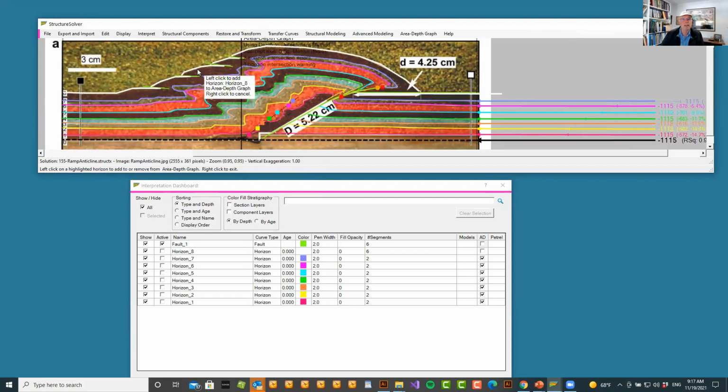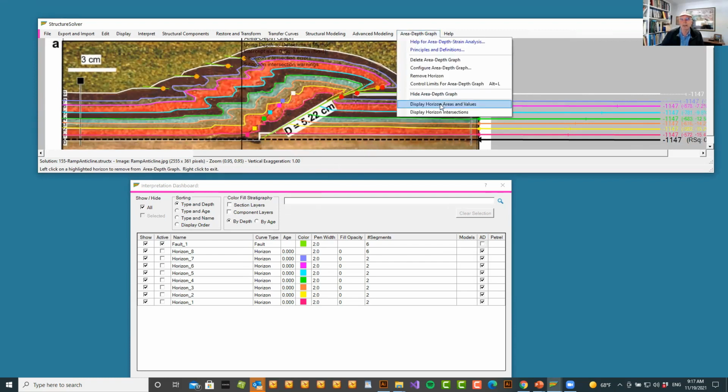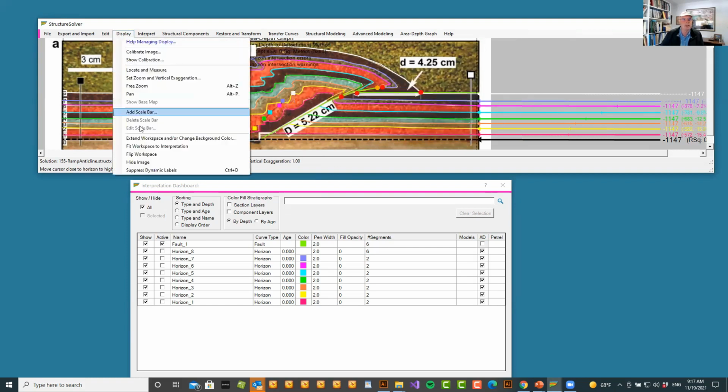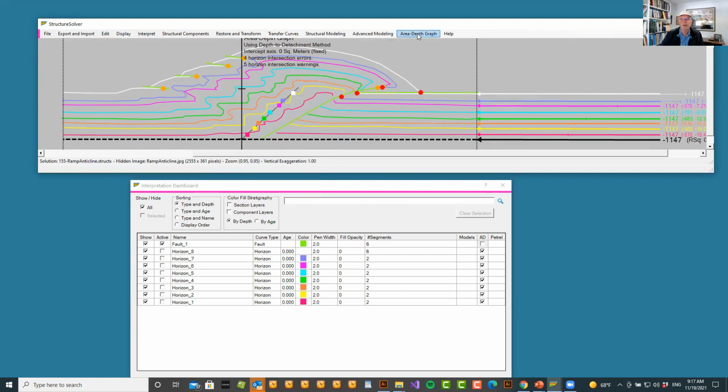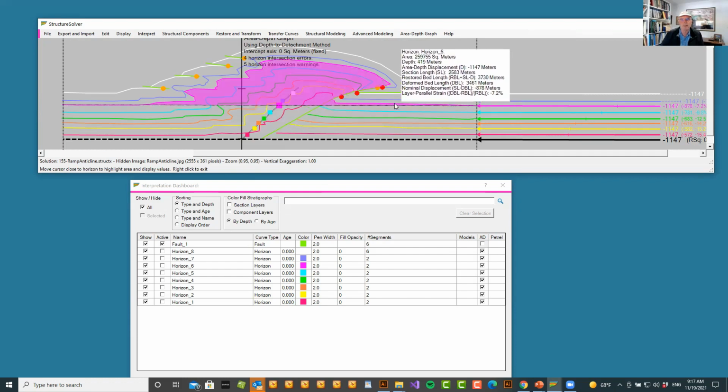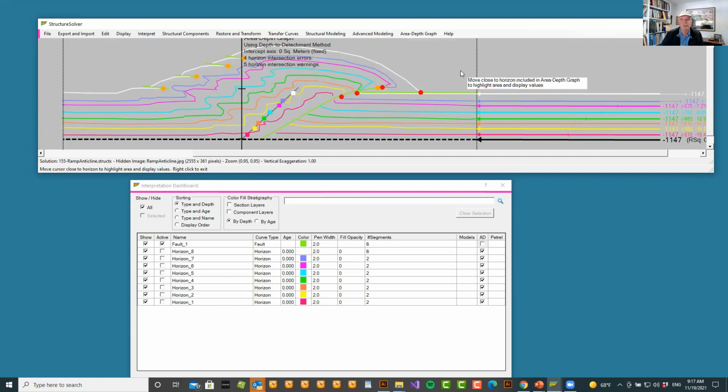and that's planimetering now the areas of each of those beds. So you can see the bottom one here. Let me just turn the display off so you hide the image. The bottom one is a small area. As we move up, the areas get bigger and bigger. And the areas are being plotted on this curve here of area horizontally versus depth vertically. So where that area goes to 0 is the detachment. And so we're accurately figuring out where the detachment is.